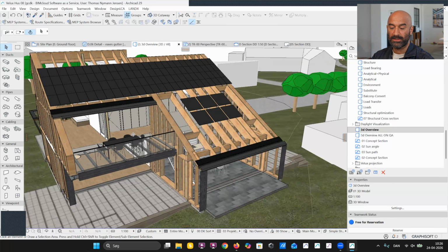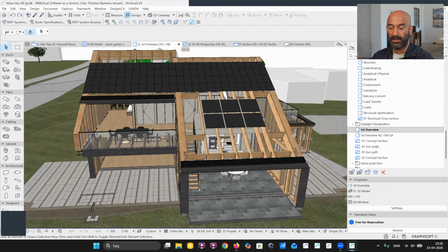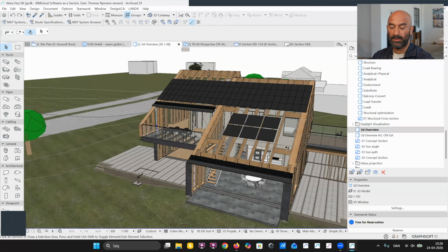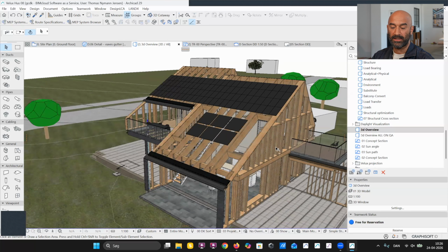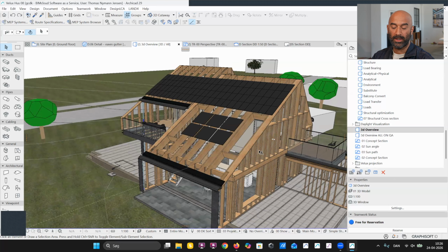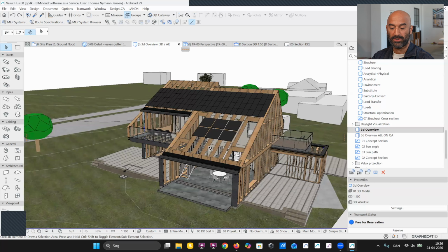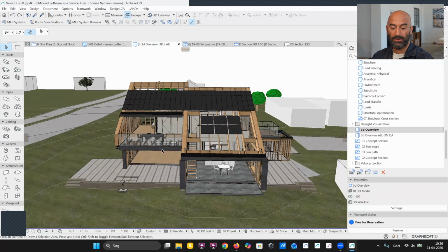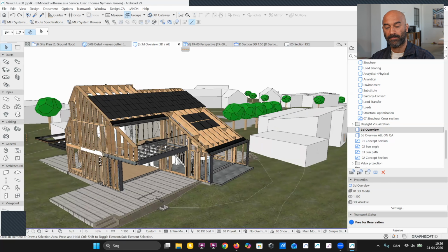So this is all inside my 3D roof, and this is also what cuts through the insulation of the roof, as well as those wooden columns in the gable that we could see before, which cut out a section of my insulation layer within my wall. That also means that the volume of the insulation will not be calculated where the column is placed, because if there's a void, it will not be measured as volume for those components. That means that you'll get the right quantity takeoff.